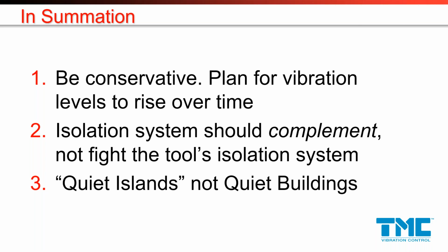What is the sensor used in the active isolator? So a couple of ways to go about it, really two different technologies. You can either measure acceleration or measure velocity. So acceleration is measured with accelerometers. Like you'd have in a car an accelerometer to deploy an airbag, you can have extremely sensitive accelerometers to sense acceleration. But the other way is to measure velocity instead.